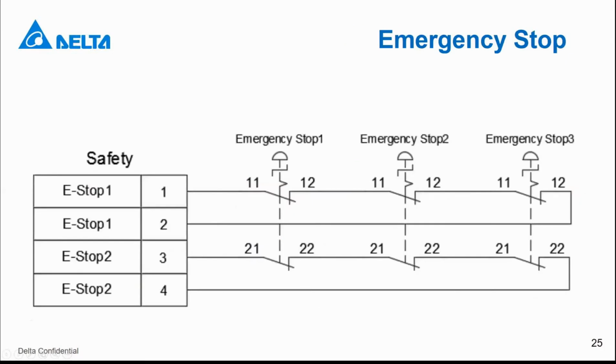And next is the emergency stop. This must be connected. Sorry. So it's a 2-channel emergency stop. Both channels you need to connect, then it will work. And if you want to connect more emergency stop buttons, then you can connect them in parallel like this.